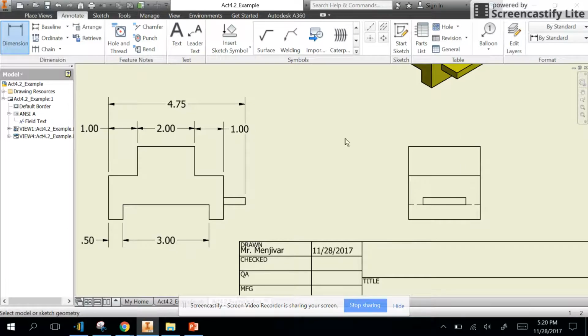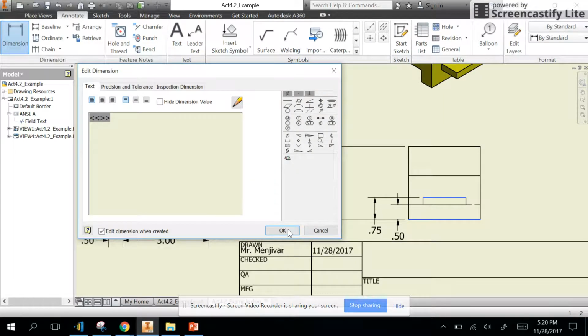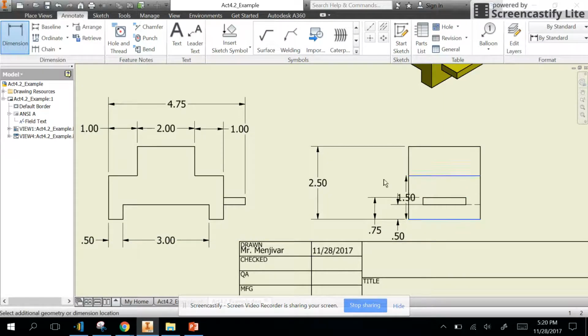I'm going to show you guys datum dimensioning on this side related to the height. I'm going to do overall height, and I'm going to put it far away in the shared adjacent view. The reason why these aren't in adjacent views is because this shows where the object is actually happening, where the contour is occurring. I'm going to go ahead and I want to know how far from bottom to top. That's 0.5 away. I want to know from bottom to the top of this. It's 0.75. I want to know from bottom to this. It's 1.5. So I'm doing datum dimensioning because I'm starting from the same point. That's called the datum point, and I'm going to the next step up.